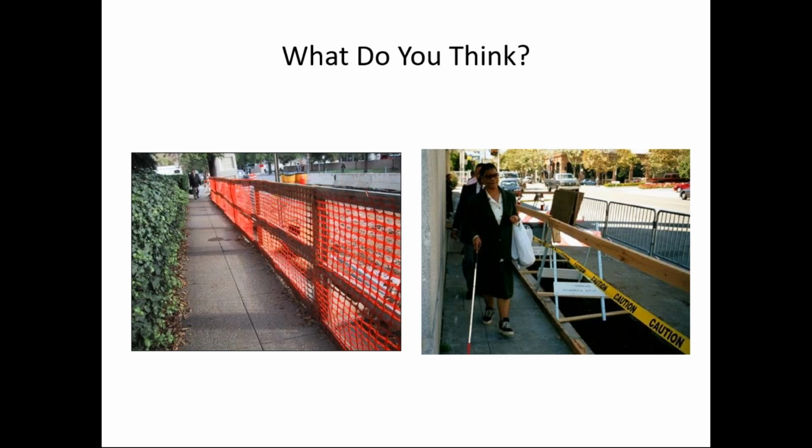So here's a couple examples. How about the one on the left first? Let's say this is 5 feet from the hedge or the landscaping here to the barrier. And let's assume this is a 6-inch high piece of lumber here. I would say that seems to comply with the edging requirements. We have 6 inches. It's not clear that these are attached or fastened, but assuming they're fastened to the surface and interconnected, that would be an appropriate